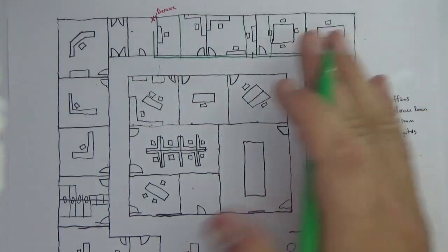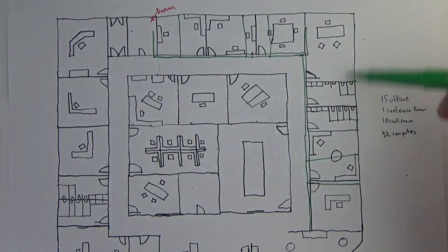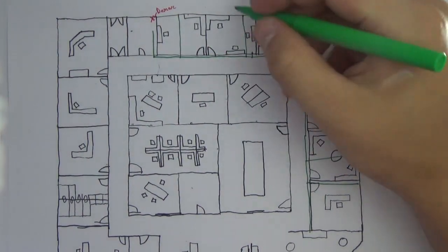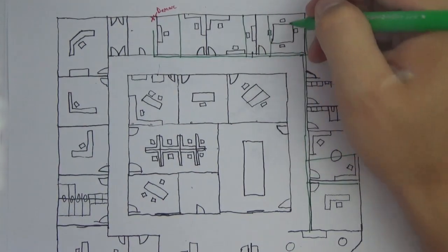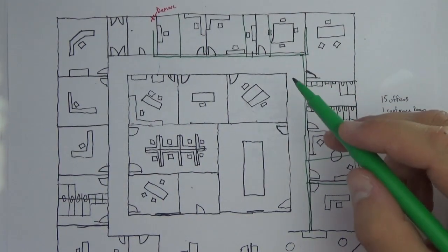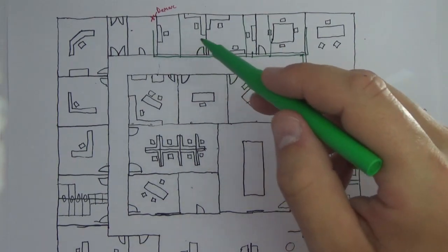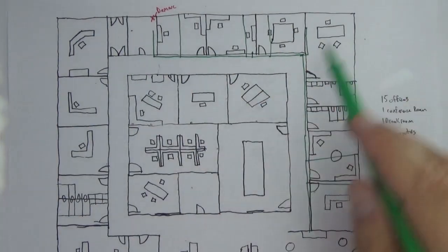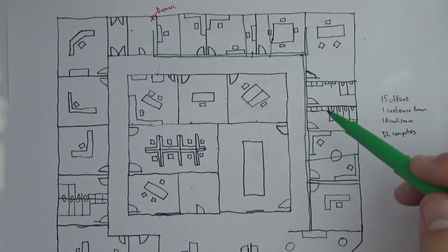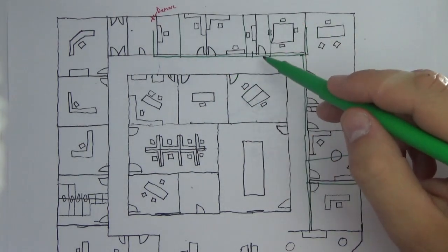Now I'm going to leave the rest of the map clean for just a moment, but we've got all of these different drops into all of these different rooms. You know, and this guy's going to have 3 in here. This guy's going to have 4 in here. It is easiest if we're running a bunch of cables together in the same thing. So instead of running a different path for every single drop, it's good to bundle things together so that we can get them more efficiently to a location.